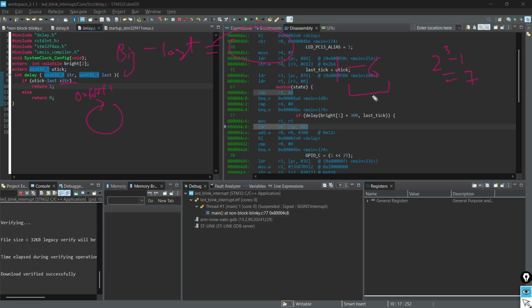What the computer does is it changes it into 2's complement, that is radix complement. -6 is simply 110 in binary 3-bit. To convert it into radix complement, the computer first converts it into diminished radix, which means flipping the bits. Now this is diminished radix, 2 to the power n minus m minus 1.